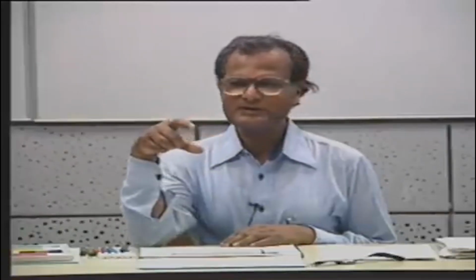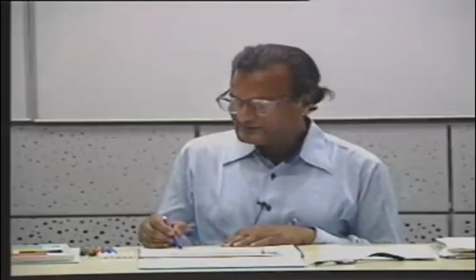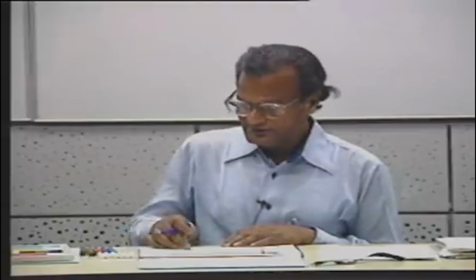What is VCB? VCB is VCE minus VBE, and therefore if you increase VCE, VCB also increases, and you know that at a certain point avalanche multiplication or Zener effect shall take over, and this is why there is a slight tendency of these curves to go up. If you go beyond this, well, it will go like this.